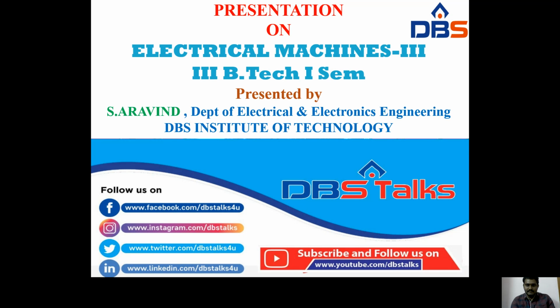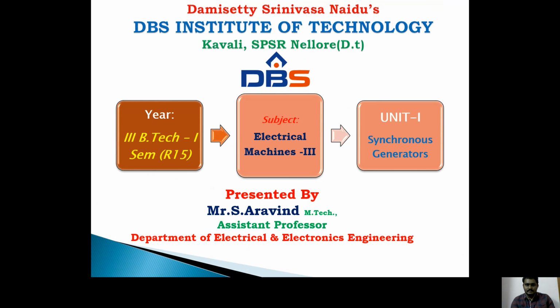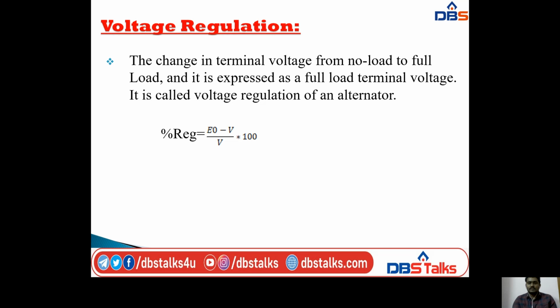Okay, so firstly we will see what is voltage regulation. Voltage regulation means the change in terminal voltage from no load to full load, and it is expressed as a fraction of the full load terminal voltage. It is called the voltage regulation of an alternator.